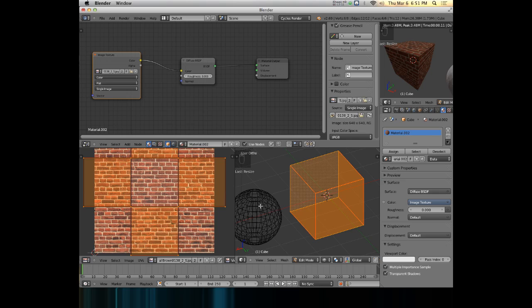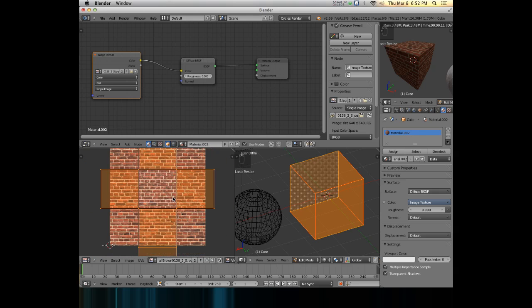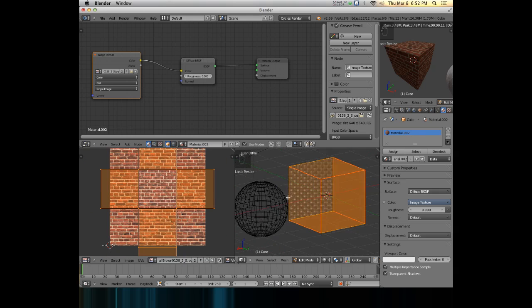Any really hard edges, or edges where there's a change in material, are another place where you can hide seams. And this is just one way of adding a texture. You can actually do texture painting as well, which is fairly common, and then you can just paint the seams over and it'll blend together seamlessly. We may get into that in this class, we may not, depending on how we're doing on time. But these are just things to keep in mind as we're working with textures and UVs.